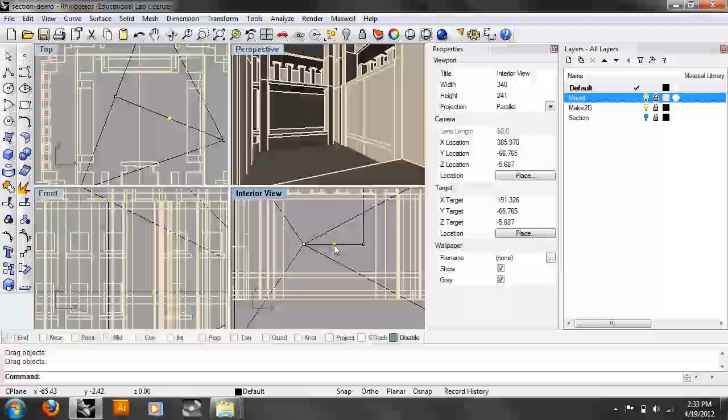Say you wanted to take a view from standing at street level, up 4 floors back. How would you make the lines vertical? You make the Z's the same, and then you have to adjust the focal length. But if you make the Z's the same, won't it be like you're 4 stories high looking at the button? Well, you could put your camera at street level and keep the verticals the same. If you want to be aimed directly at it, you'd actually have to move up pretty high. Because if you make the camera at one point and the target at another, it's going to introduce that distortion. So you have to be sneaky.